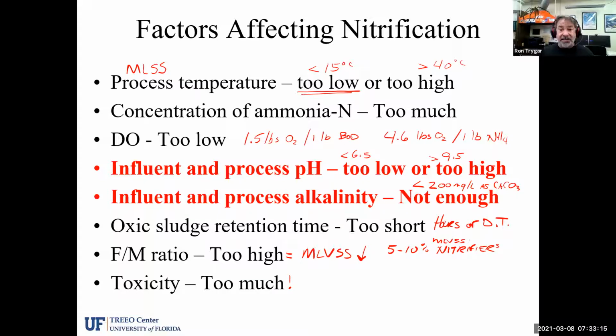Whenever we drain tanks, if we have empty basins or basins that have a lot of water in them or sludge that we are now going to return back to the head of the plant, when we drain those tanks back, we have to measure things like the pH, the alkalinity, the amount of nutrients that are in that. Did we have a reversion back to ammonia in that basin? Are we going to slug load our plant with ammonia, because we've held on to a basin for months and it's been sitting there getting fermented, and then we return that back to the plant? We could actually be causing toxicity in our treatment plants just from our own activities.